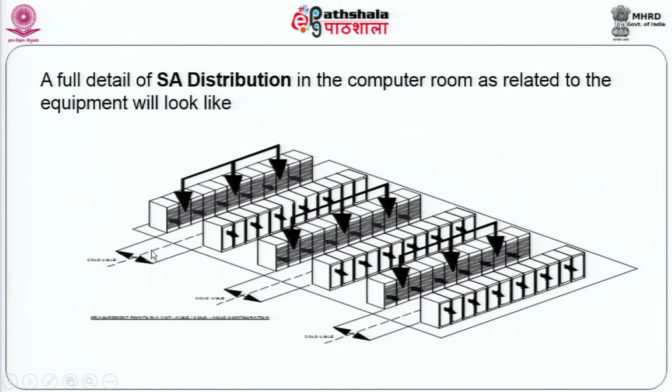So, this is called the cold aisle, this is called the hot aisle, this is called the cold aisle. Now, this is a typical layout of a data center room. People like ASHRAE, the American Society of Heating, Refrigeration, Air Conditioning Engineers, have invested millions of dollars in finally coming to this kind of a thing as a recommended device for layouts, and I am happy to say that very rarely you will see a contradiction from this.